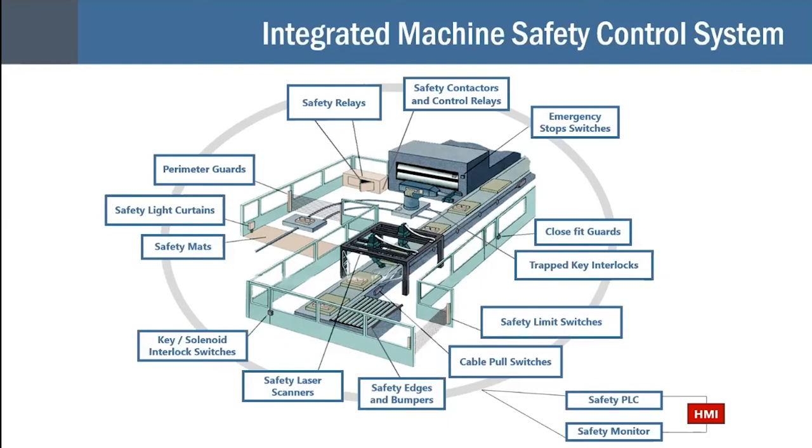Now, doing machine guarding inspection and audit, it's difficult to check this unless you're a machine guarding expert and specifically knowledgeable in the electronic systems of a safety control system. But some of the things we do see, and again, this is on interview with the operator and the maintenance people with the machine, is that perhaps the E-stop was wired directly to the on-off circuit and it's functioning as an on-off switch.